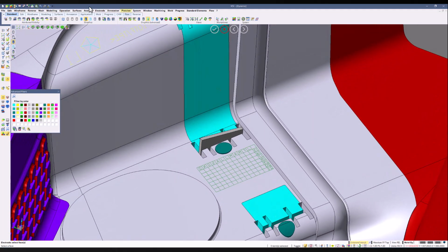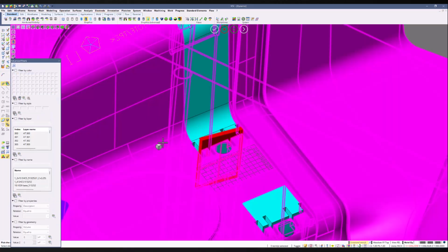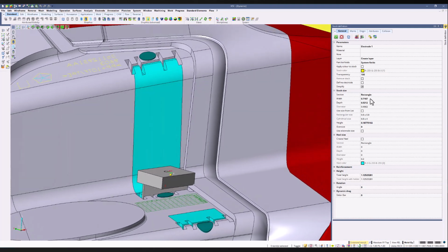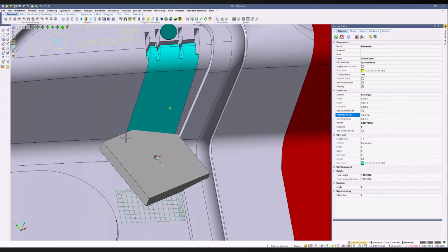and then within the stock definition, I'm going to create my stock, and that's where I'm going to apply an extra reinforcement to this. So I'm picking the tip, I'm going to pick the workpiece and the insert, and you can see how it defaults to stock. I'm going to use a custom size here. So a preset bounding box size I have, I'm going to go 1x2. And you can see how it changes that size there.